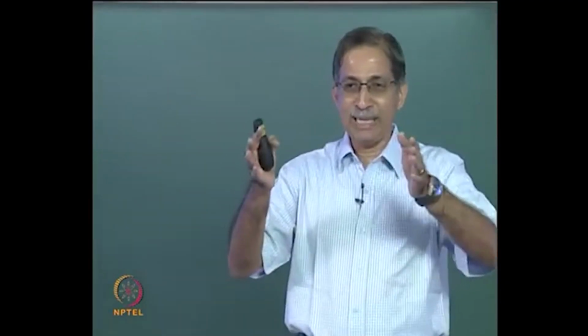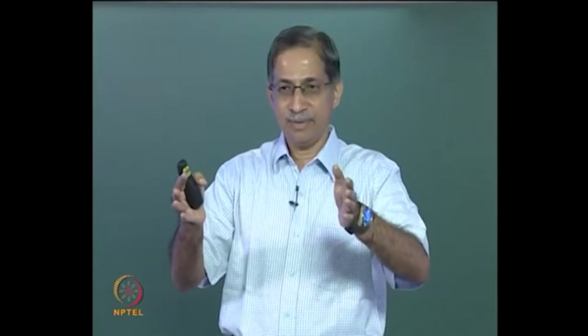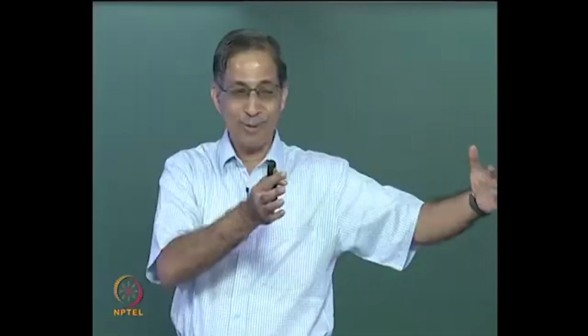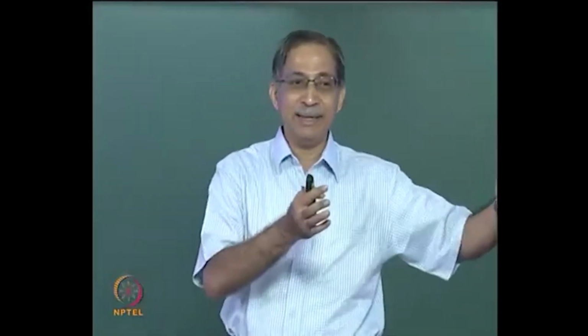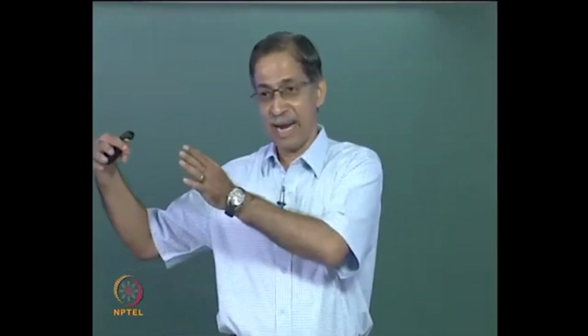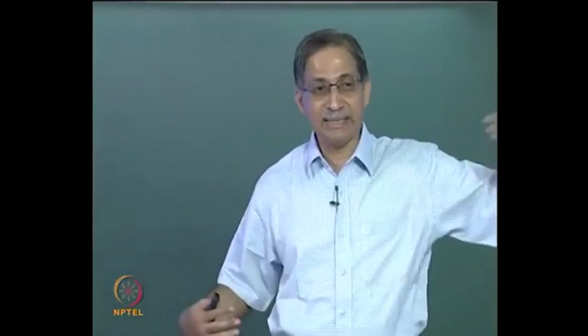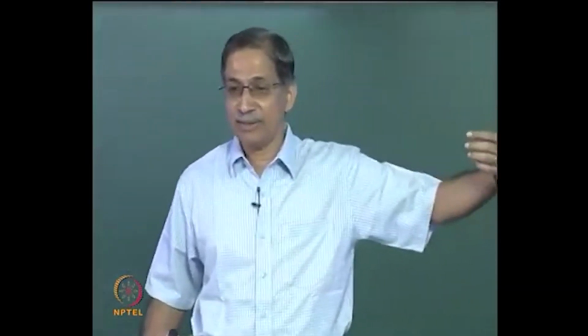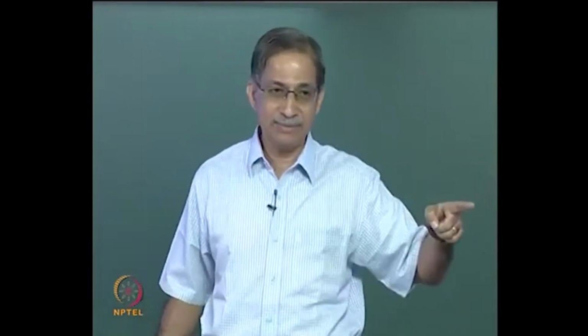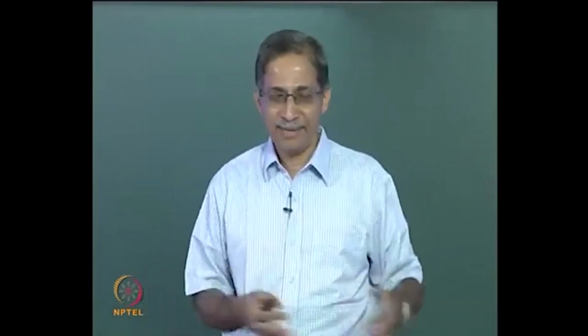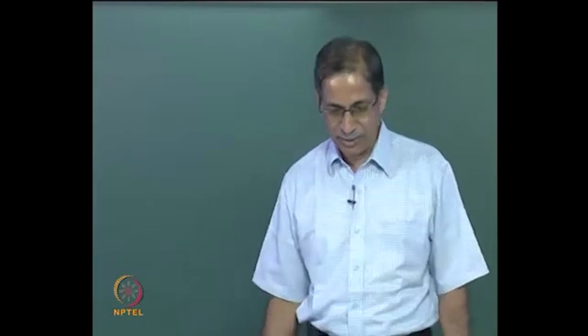The joint displacements here are 0 because you arrested everything. The joint displacements in your original structure are non-zero. So obviously if you do superposition, the equivalent joint loads should act in such a way that you end up getting the same unknown displacements in the original structure at the joints, not in between, and that is the basic principle of equivalent joint loads.